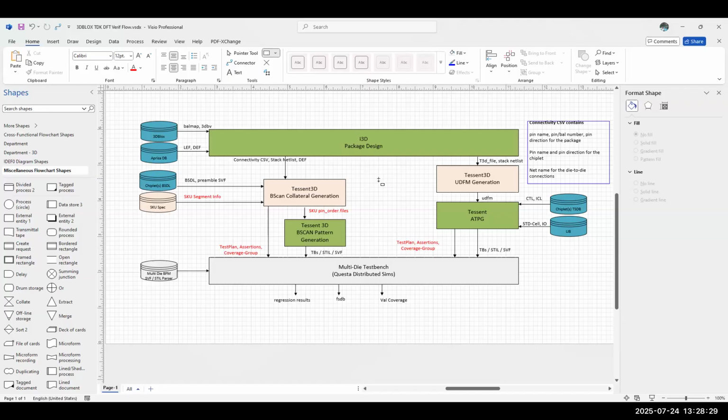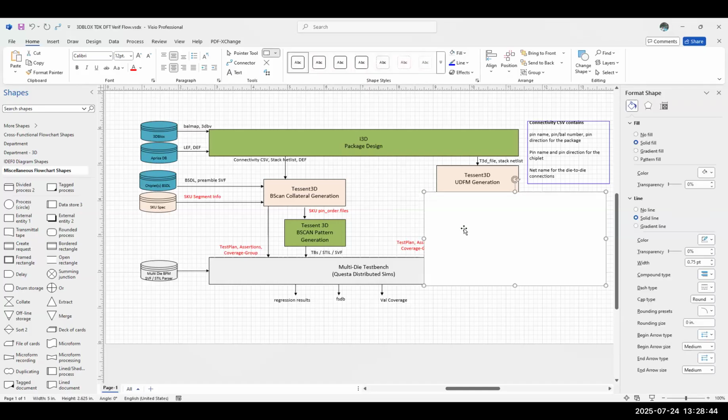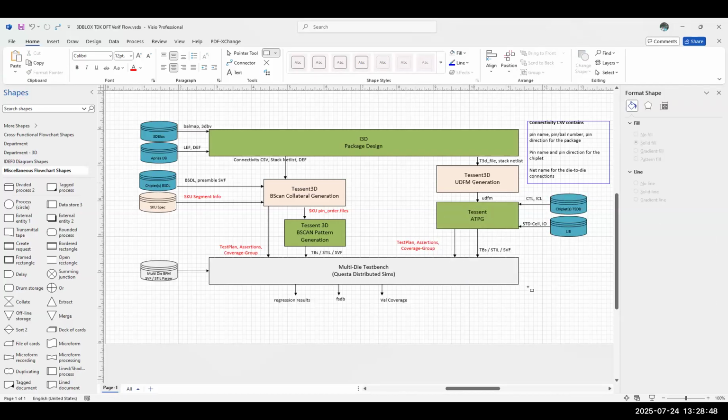Well, actually, if it's an external SerDes, those pins are going out of the chip, so in theory they could be used for testing if you put them in a bypass mode. Yeah. But the die-to-die interfaces, you don't have direct access to those through the pins. But there are techniques for generating patterns on each of the chiplets, so you could test those interfaces.